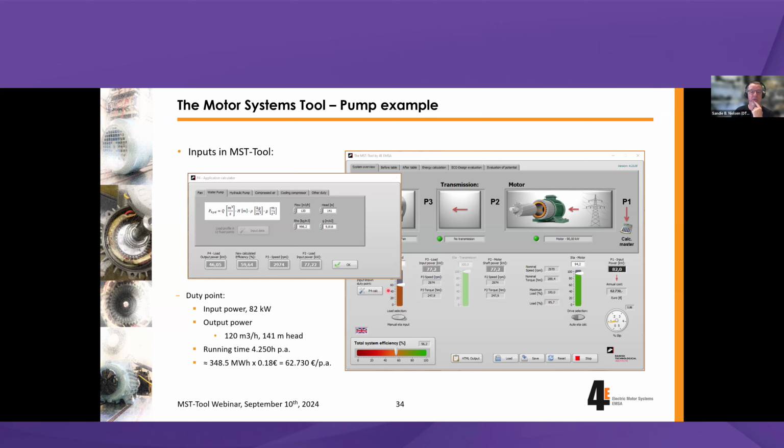So when you push the P4 calc down here, this splash will come up, and there I will have the 77.2 from before put into the model. Then when I fill in these 4 numbers here, I calculate the hydraulic power to 46.05 in this case. When I know this number and this number, the division is quite easy, and therefore, without having a pump curve, I can see that the efficiency of this pump would be around 60%. The speed in this case comes from the motor calculation, 29.74.